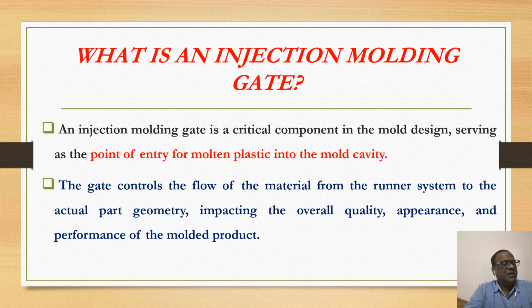If the design of the gate is not proper, we will get different types of problems, like distortion, warpage, sometimes ejection problems, then weld line formation, all these things.